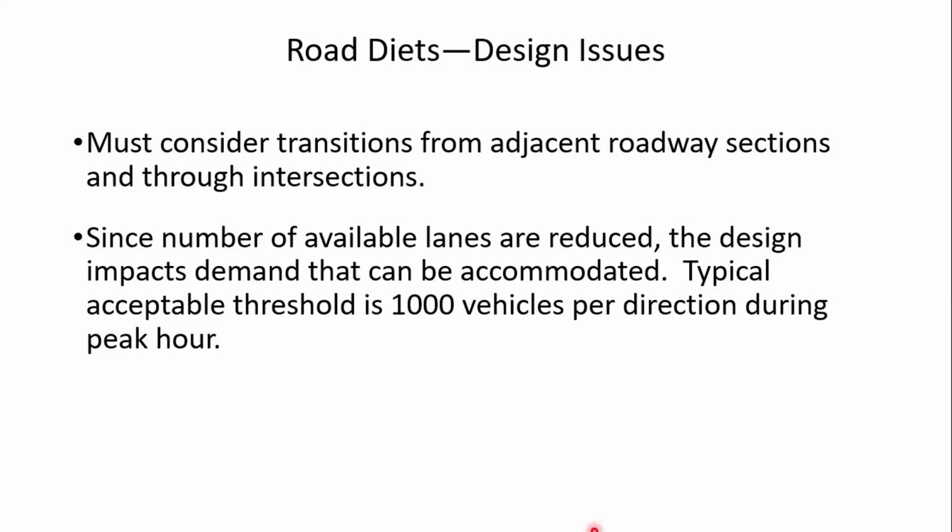We have a roadway here in Morgantown. It's a 5-lane cross-section, kind of an entry to the West Virginia University Hospital Medical Complex, and for decades people have been suggesting, this would be nice to do a road diet here. We could reduce traffic to 1 lane in each direction. We could put bicycle lanes on the outside, and in the center, instead of a turn lane, we could put an attractive median to make this a nice gateway to the university campus.